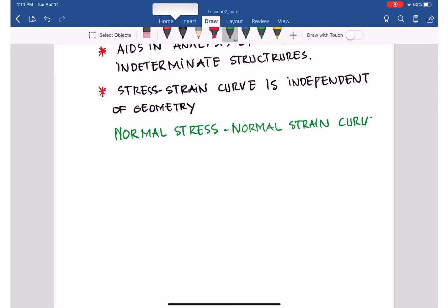It is the stress created by the normal force perpendicular to the cross-sectional area. Normal strain, for example in a centrically axially loaded member, is the strain along the longitudinal axis of that member, in the same direction as the normal stress.